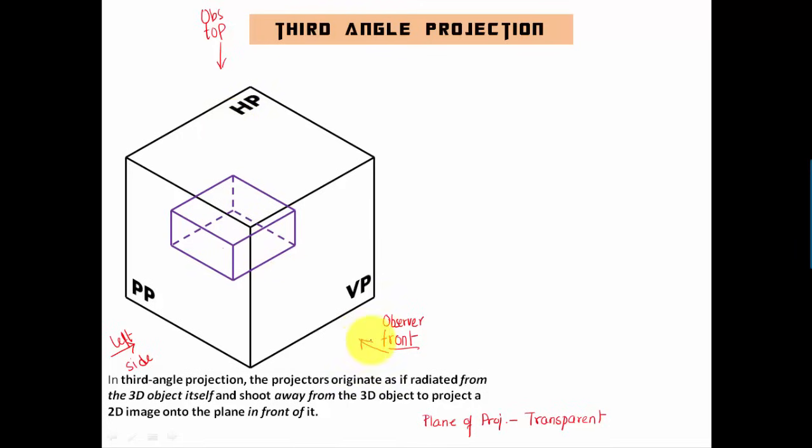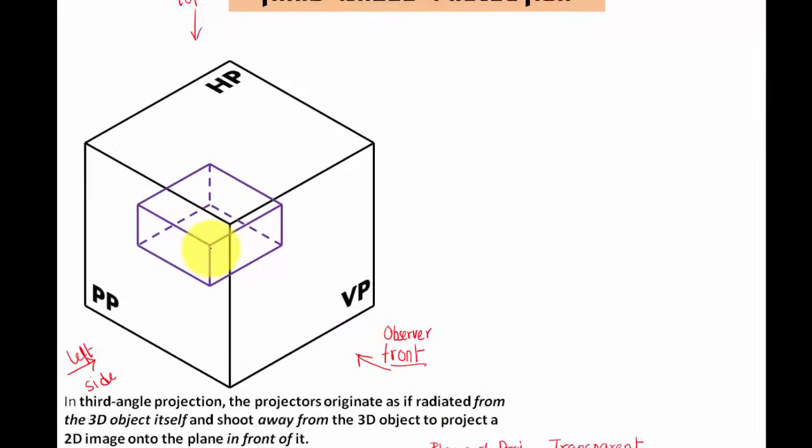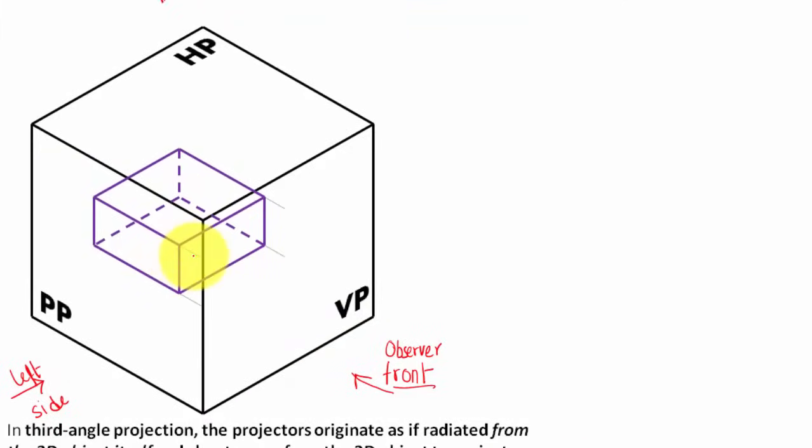Initially we're going to be looking at this object from the front, and let's draw the projector lines towards this vertical plane in the backward direction, something like this. And these are the intersection points with the vertical plane, and obviously all these projector lines are going to strike this plane, making 90-degree angles. Obviously that's why this is an orthographic projection: apart from being parallel to each other, the projectors also strike the plane at 90 degrees. So this was all about the front view.